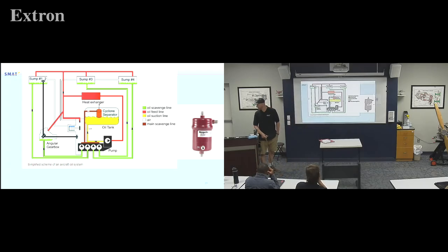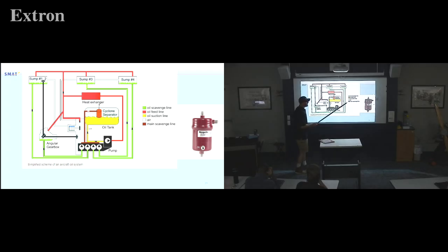And the idea is, this says oil, so oil's coming out the bottom. We want liquid oil with no air in it. So in the side of here, we would put our air-oil mixture, and basically it just comes in and spins. So out the top of your tornado, if you will, your cyclone, it pretty much should be just air, right? There shouldn't be oil, because the oil is going to be in that spinning, and the weight of the oil gets spun to the outside. So basically our air is going to come out the top, and our oil is going to settle down to the bottom. So that kind of gives you an idea.